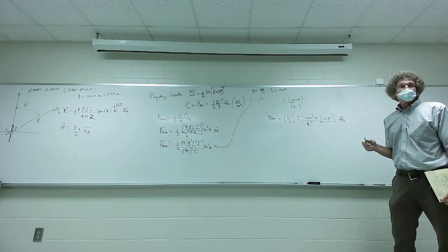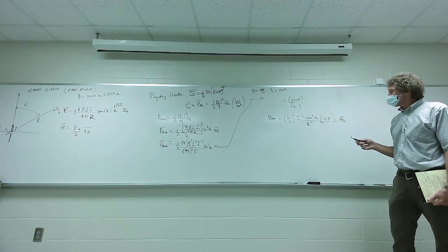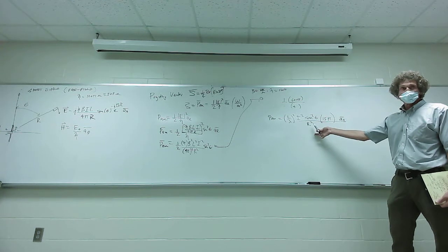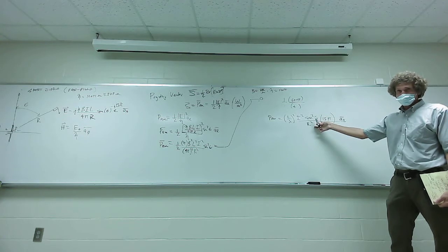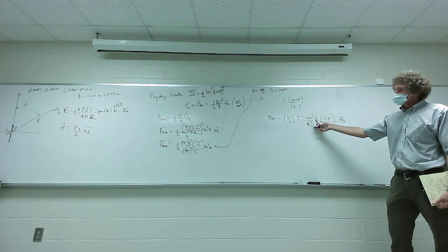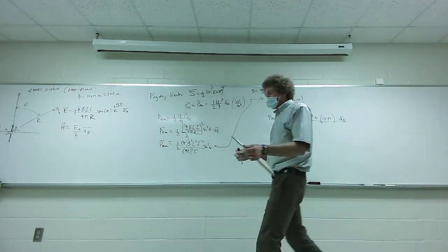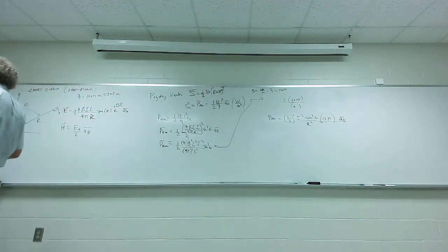The I squared really brings out that the power density is proportional to the square of I, inversely proportional to the square of the distance, and directly proportional to sine squared. With me, class? Now I want to do that. This is for the short dipole that is so important. There are a lot of different small antennas that all have the same type of sine squared pattern.